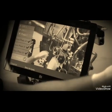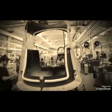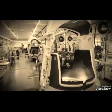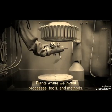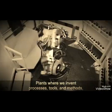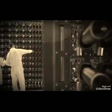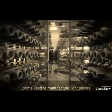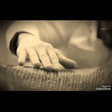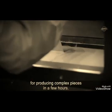Similarly, the development of ceramic matrix composites, CMCs, involves weaving ceramic fibers into intricate three-dimensional structures. The preforms are then infiltrated with a ceramic matrix material, such as silicon carbide or silicon nitride. Afterward, they undergo consolidation processes, which typically involve high-temperature densification. The resulting CMCs boast exceptional thermal stability, high temperature resistance, and low thermal expansion coefficients.